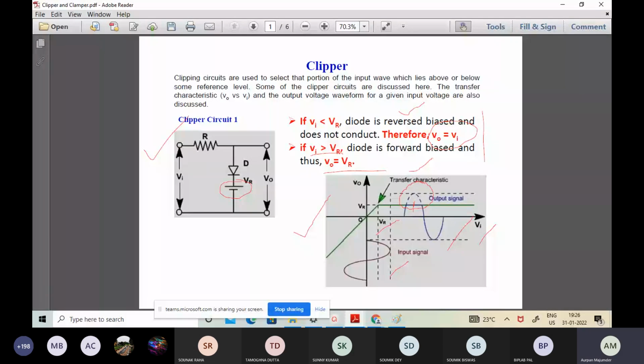As you have studied about transistors, the AC signaling operation of transistors and single stage transistors, there is a very important point, which is that you need to bias the transistor properly. Why is this biasing so important? Because when you feed in a signal, let us say you have a common emitter amplifier, you put the signal at the base and get the output from the collector terminal with respect to the emitter.